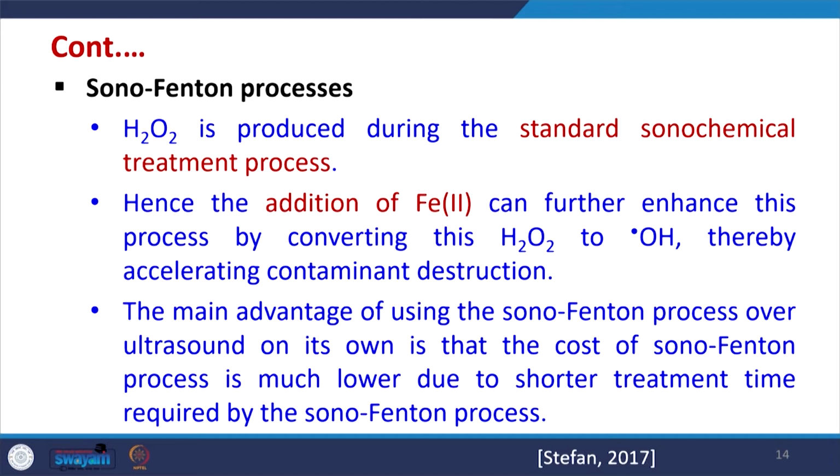Then there is also the sono-Fenton process, in which H2O2 is produced during the standard sonochemical treatment process. Hence the addition of Fe2+ can further enhance this process by converting this H2O2 to OH radical. Thereby it accelerates the contaminant destruction, and we are able to mineralize the contaminant very quickly.